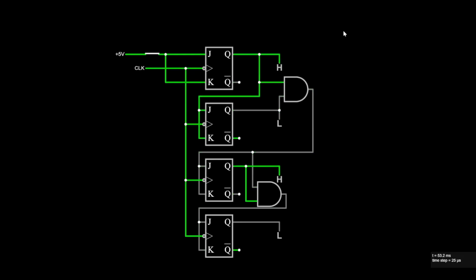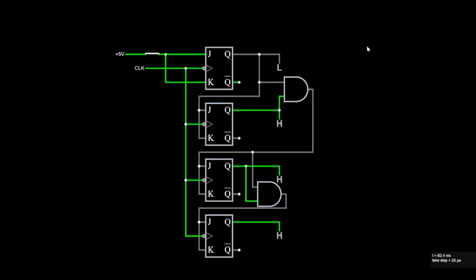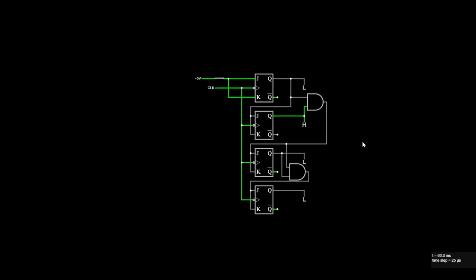Or, if you're a fan of finite state machines, you could just make a little counter here, right? Our 4-bit counter here can only support up from 0 to 15, so 16 numbers total. So I don't know how well that'd work for a turnstile, right? Oh, we got 16 people. Time to reset it.